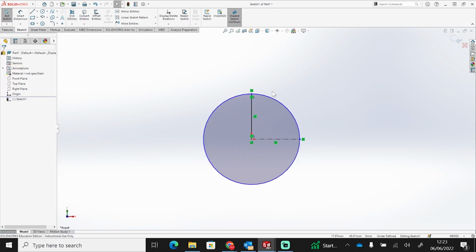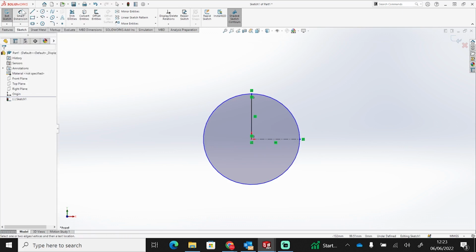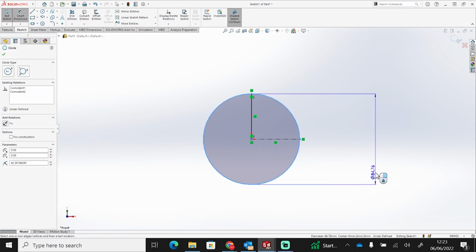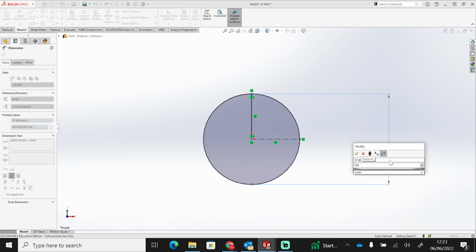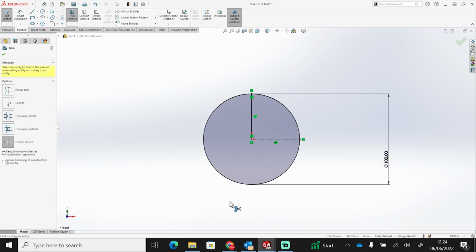Now, what I want for the back section is effectively just this sector or pie section of this circle to be able to cut out and extrude it round. But first of all, I need to set a size to this. So it's going to be a diameter of 100. Set that diameter like so. Now we've got that, I can trim away what I don't need, which is all this section. If you're using the trim function, I like to use trim to closest, but whichever one you find easiest. That leaves me just with that top section of that circle.